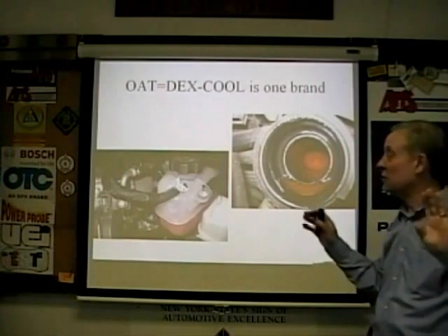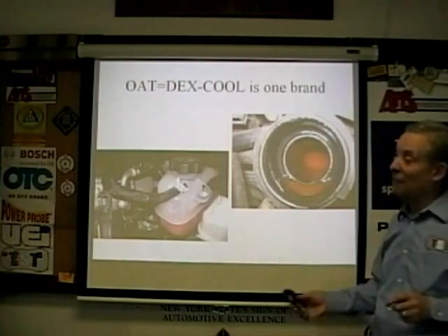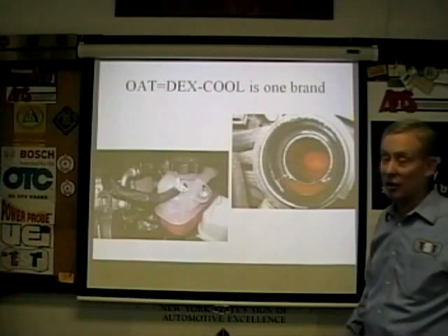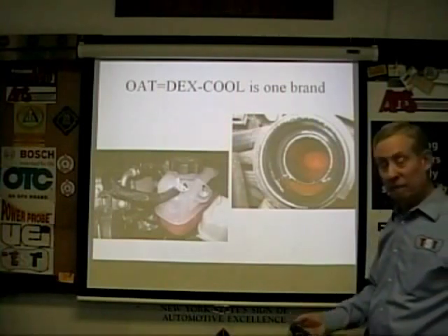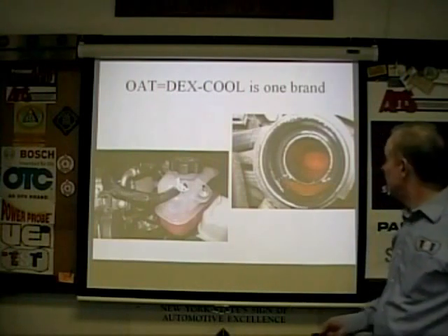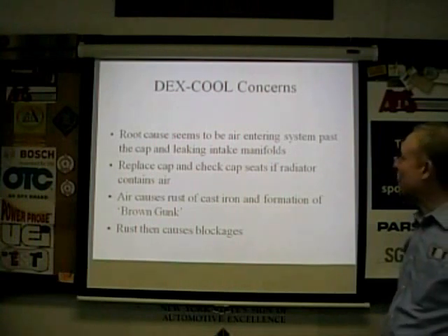Don't get stuck in a situation where you put a thermostat in that car, drain some coolant out, put the right stuff in, it's now incompatible, and the engine ends up with jello and an overheat and needs a motor. Tell the customer you cannot do that job unless you flush it. Otherwise, you know, you're the one holding the bag. Okay.